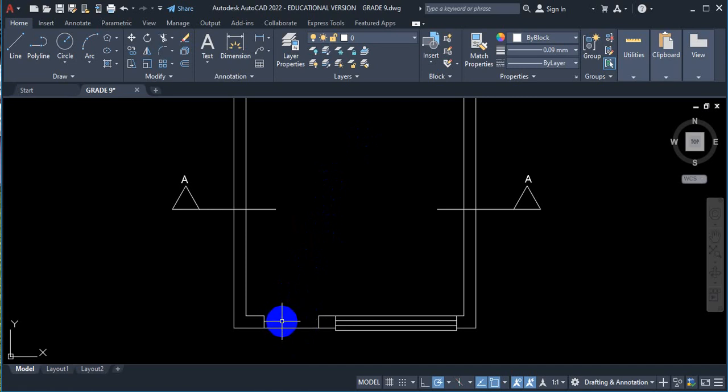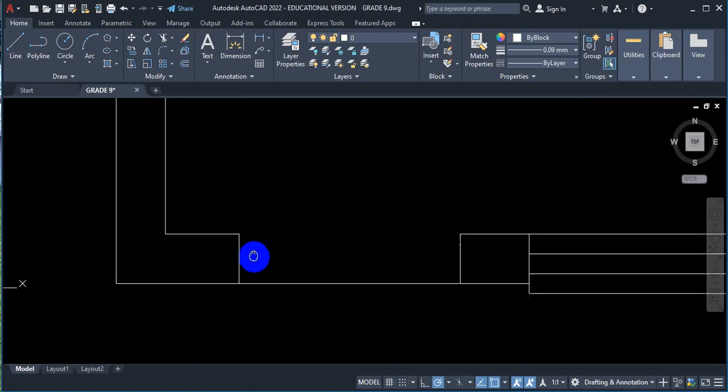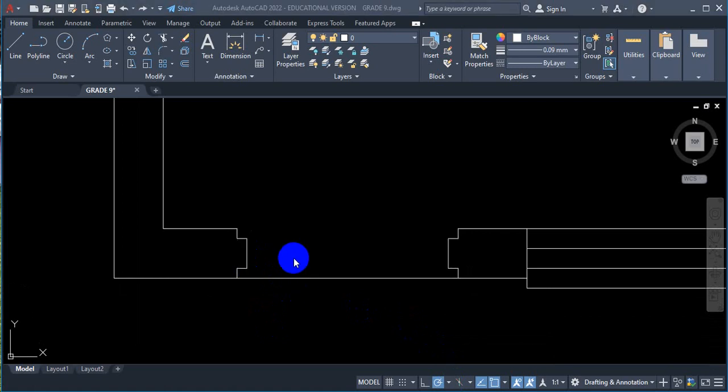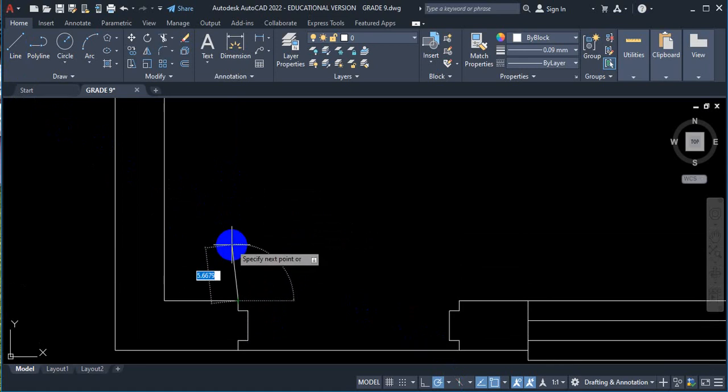So another thing that is very important, the position here, the line here or the wall is shorter compared to this wall. So the door always opens towards the shortest side of the wall, which becomes this side. So the door will open and swing towards that direction because this wall is shorter than that wall. So now we need to draw, I'll bring in the frame. So now this is our steel frame which we have constructed using 1 millimeter away. So now we need to position our door here. This is where your door will be swinging.